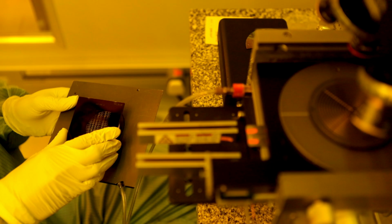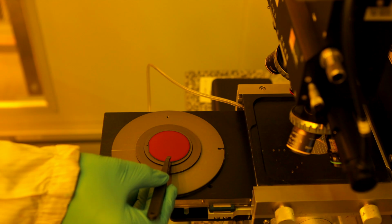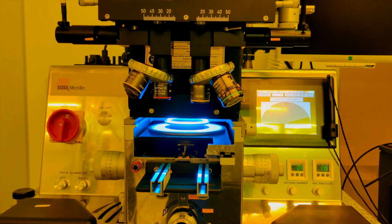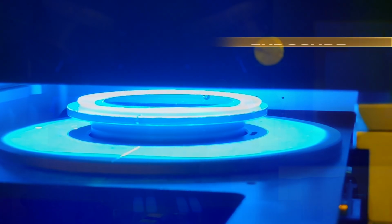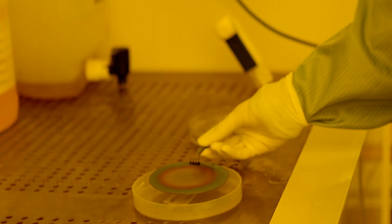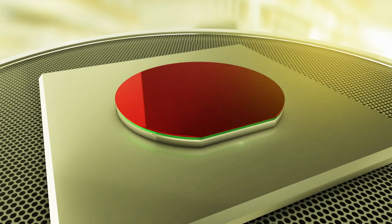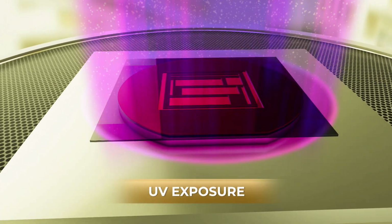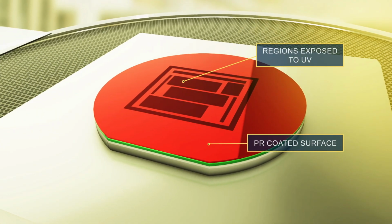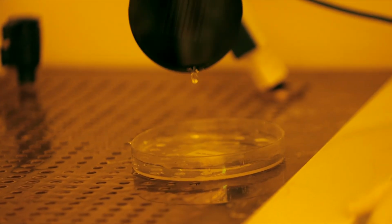After the PR has dried, the coated wafer and the mask are loaded onto a mask aligner and illuminated with UV light. Only those areas that are not masked off are exposed. After exposure comes development. The wafer is dipped in a chemical that dissolves our special chemical, the PR, only from those regions exposed to UV light through the mask. It's only in these regions that the PR is chemically altered and hence made soluble in the developer. Voila! We now have a pattern transfer.